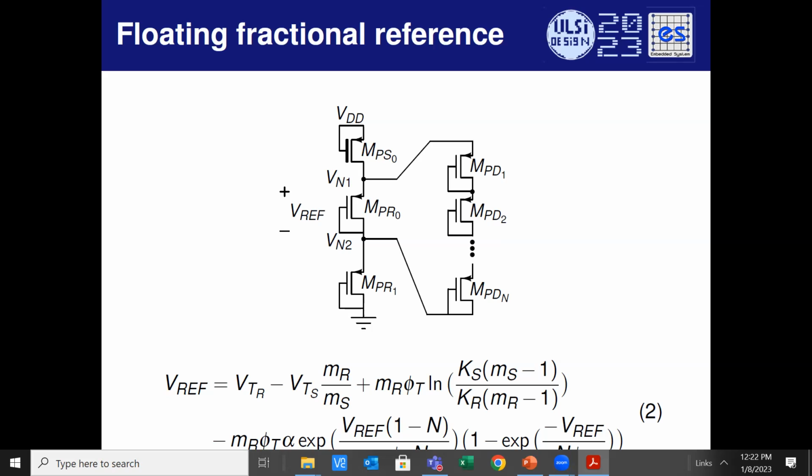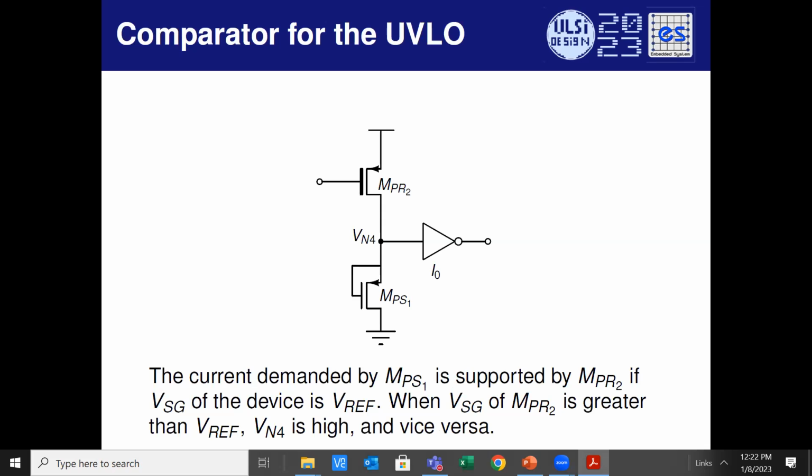So all of these corrupt the reference. The current through all of this is going to damage the value of the reference, so you'll have to be careful over there. It's also going to be very noisy for that matter. So a lot of capacitance has to be added to reduce the amount of noise in all of these nodes. Resolution, I don't know. Just a few will do. All right. So that's one part of the strategy.